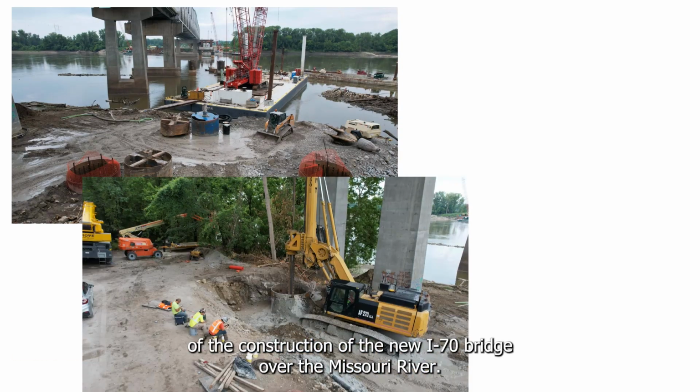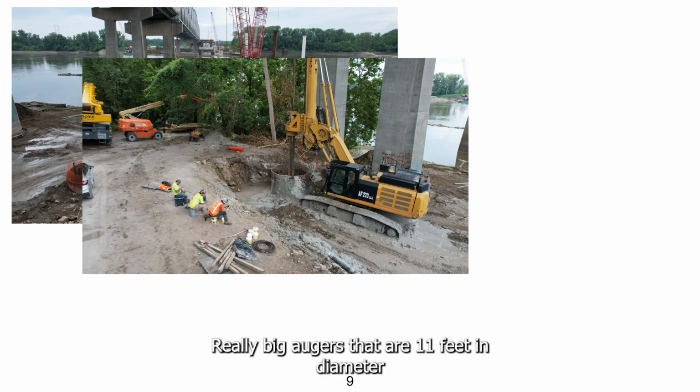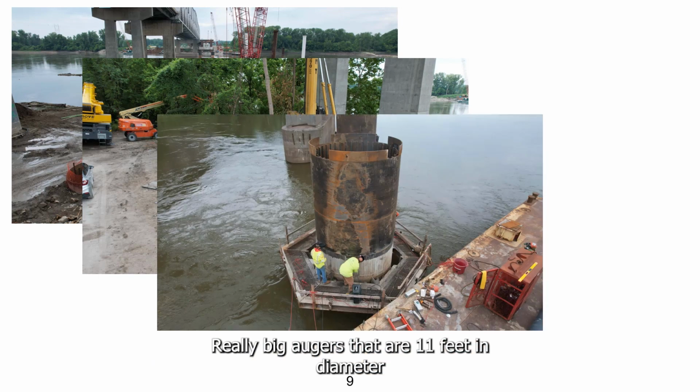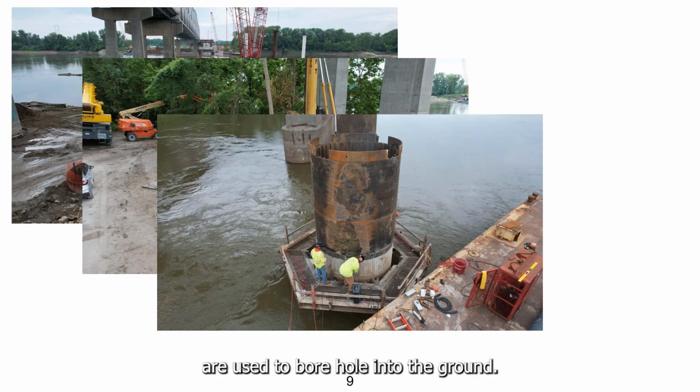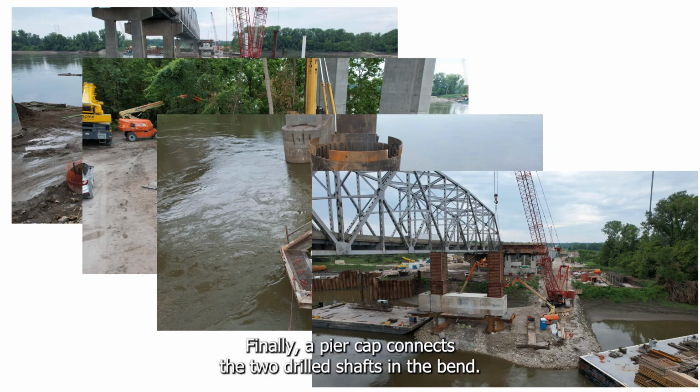Here are some pictures of the construction of the new I-70 bridge over the Missouri River. Really big augers that are 11 feet in diameter are used to bore a hole into the ground. Then a reinforcement cage is placed in the hole and it is filled with concrete. Finally, a pier cap connects the two drilled shafts in the bent.